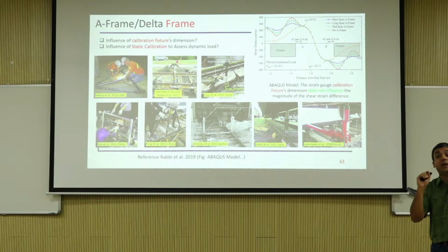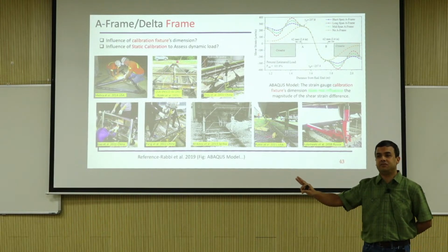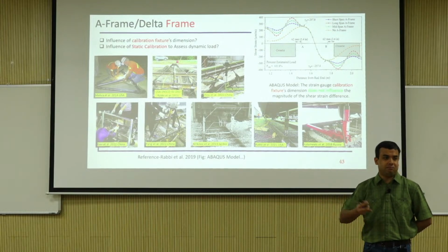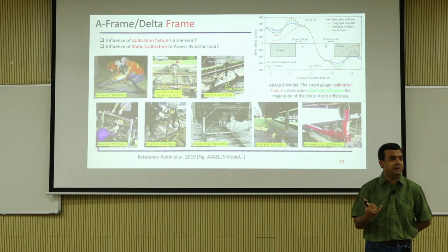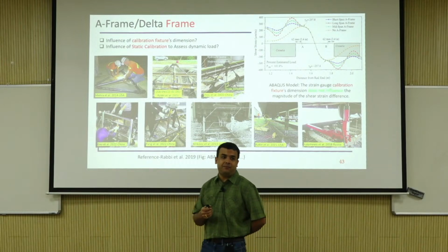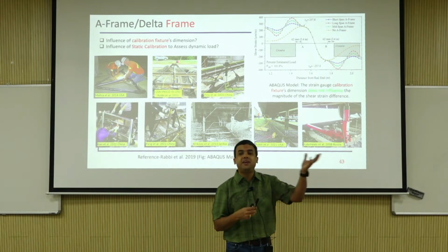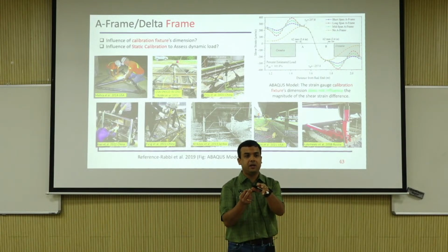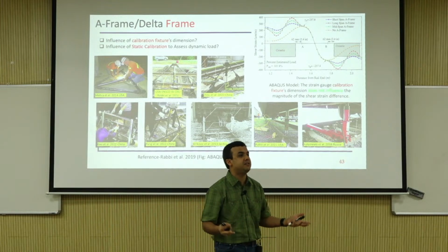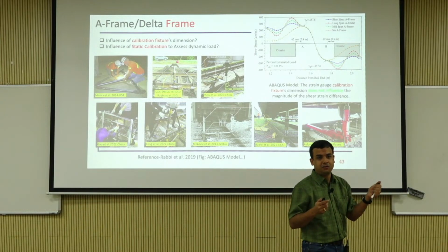Because if you know, let's just say, 1 volt is this many strains, that's fine, you can calculate everything. But when you don't have that knowledge, and you only know strain, and in the field the rail property changes a little bit, the wheel is a little bit out of shape so there is an impact load, the subgrade has changed a little bit, you cannot just predict pure strain values, right? So you have to have calibration.